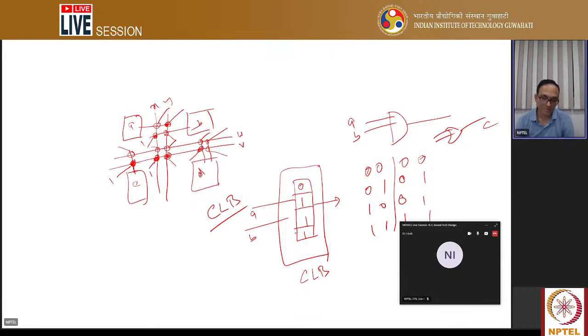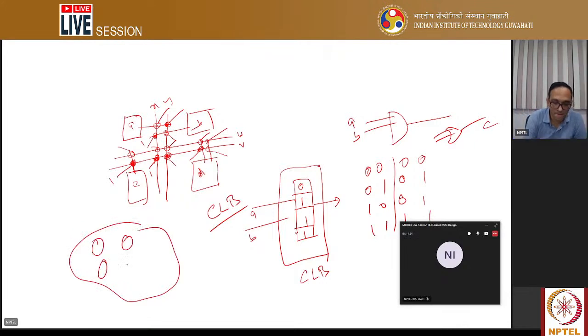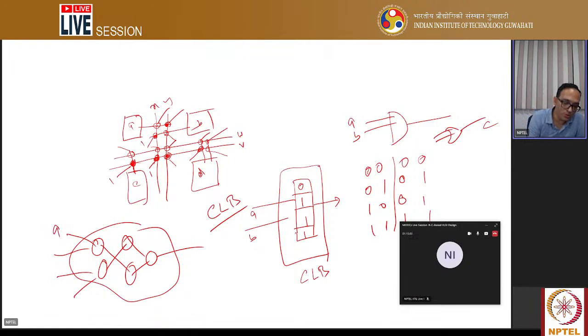This is the simplest example, but for a bigger design with 4 inputs, you can take an entire circuit, an entire design which has many gates, and map the whole thing, because at the end you have to know the input output correlation. You need to know, for ABCD value 0000, what is the output of this design? For ABCD value 0001, what is the output? And all these values you have to store in this memory, if the CLB has 4 inputs, right?